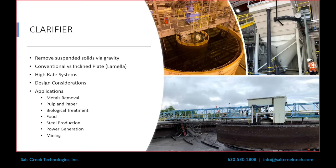Inclined plate lamella clarifiers are great because you're reducing the amount of footprint that you have for a given flow rate. But again, you need to be careful, because if you're trying to put too much solids into a unit, you can really end up with a clarifier that's slammed full of solids, or a sludge that's really dilute. So when you're picking a lamella, make sure you go through the calculations that it's going to settle properly. You want to develop a sludge that's thick enough to actually be a sludge and not just another 50% of the stream going through the unit.